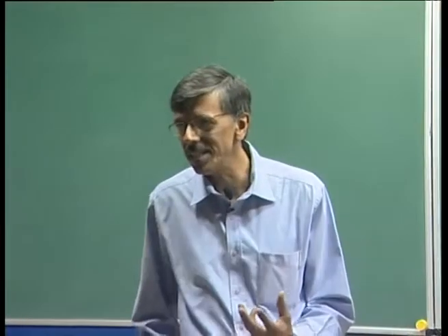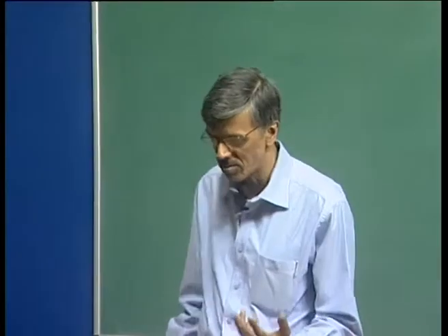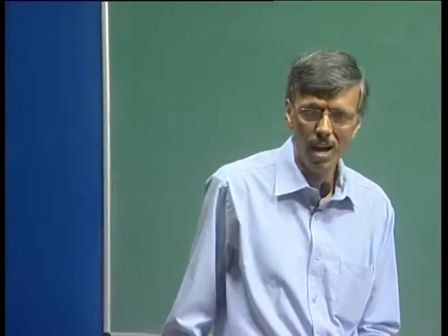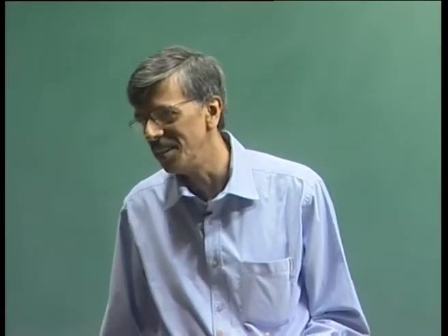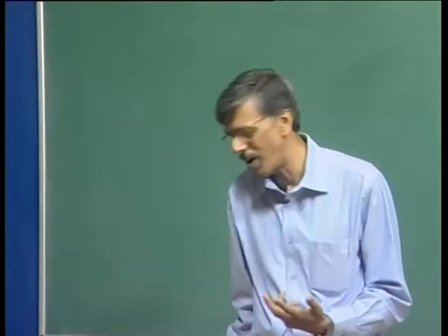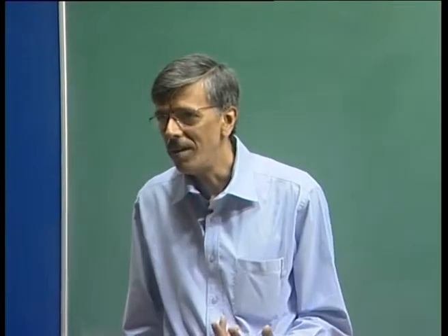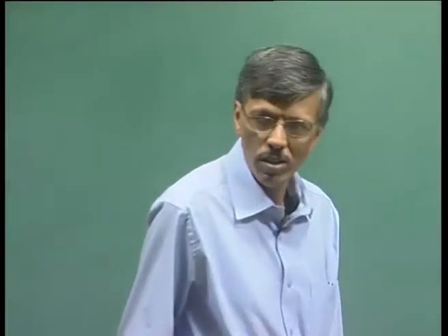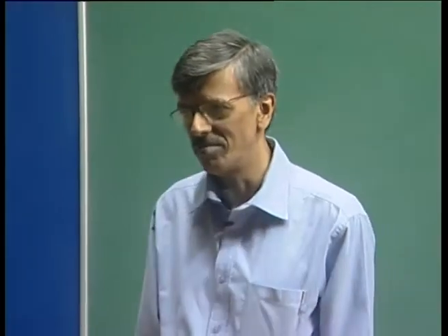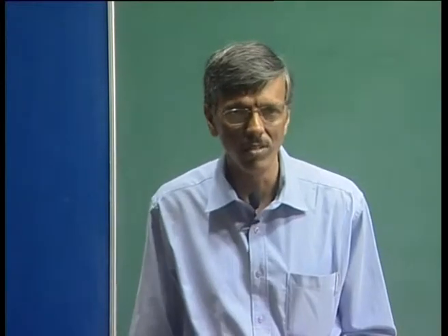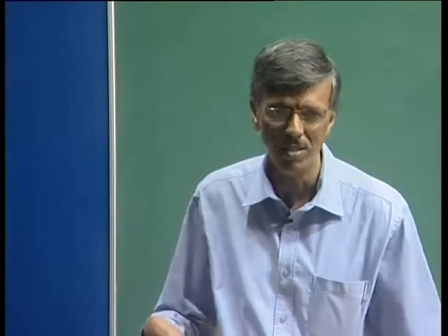So, instability is the core of everything. See, that is why in this course, although it is titled Transition and Turbulence, I have spent most of my time talking about the transition aspect with the twin object. One is, of course, all these phenomena are instability driven, and number two is to basically fight the ghost of the commonly held perception that turbulence is universal. So, it does not matter how you get there, it will all be given by a single model, which is not true.